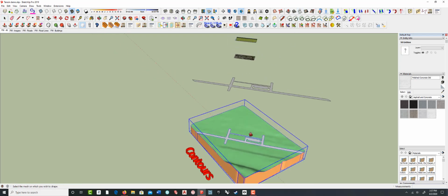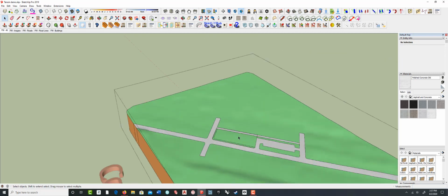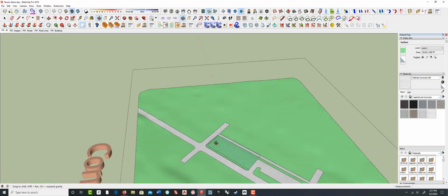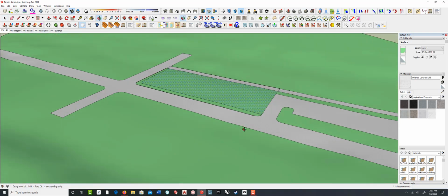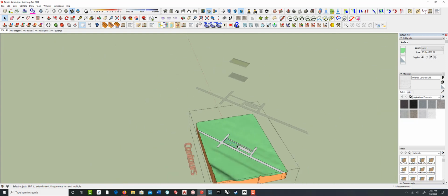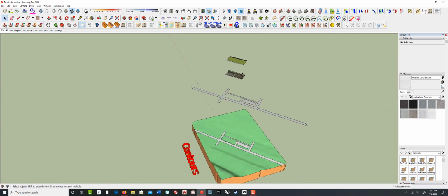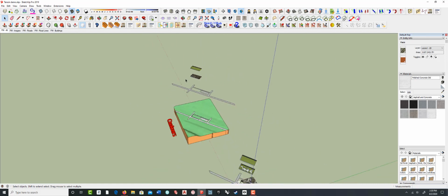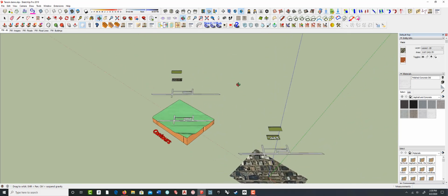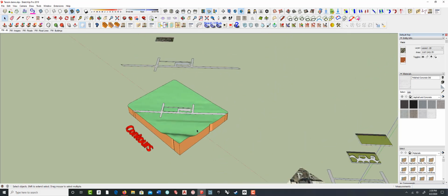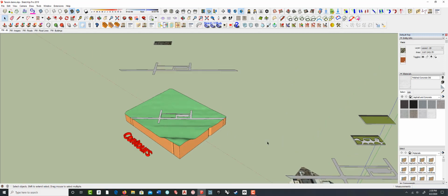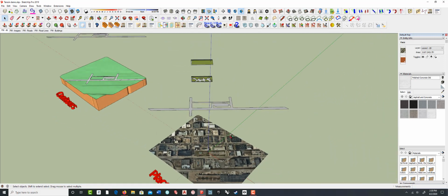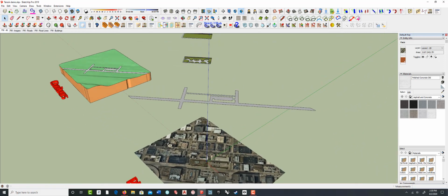Then I can come back in and add my overall site shapes to that. Again, select it, choose the drape tool, and it can be inside a group, it's fine. So basically I'm getting this to the point where I can separate that site off. And then if you want to work with this and you have your design elements already here, I could drape these down onto that terrain, or I could turn them into shapes. I'm not going to demonstrate that on this one. You'll see that technique as I move through here. So anyway, if you're working with contours, get Toposhaper, use it, it's great, and you'll see the benefit of that in a minute when I start using Artisan.